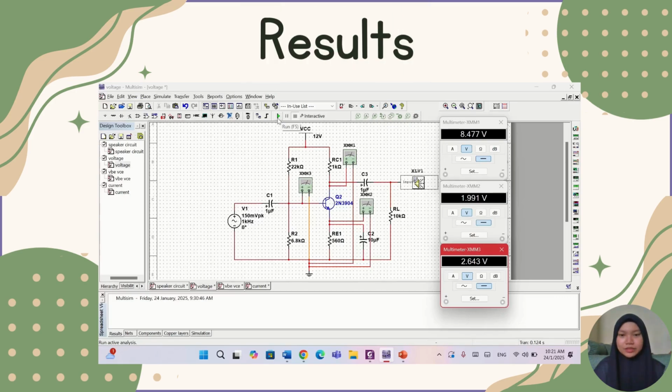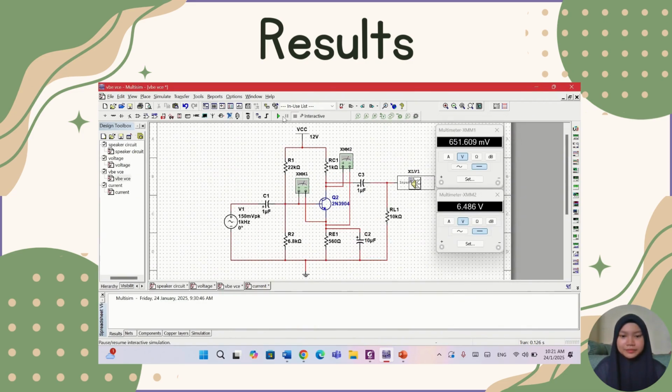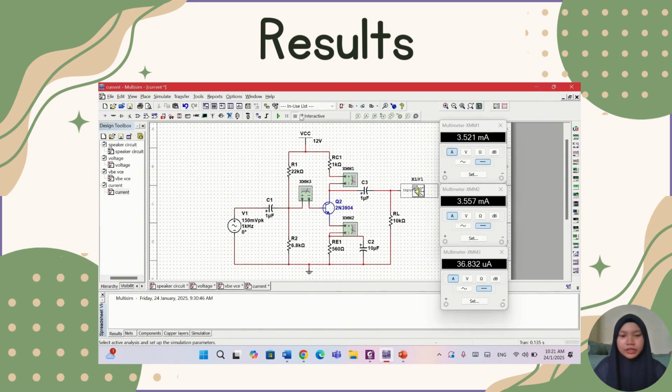So this is the simulation result from the Multisim. We use the multimeter to find the value of voltage, which is VE, VB, and also VC. Next, we find the value of VCE and also VBE. From the simulation result, we know that the value is not far from our calculation.